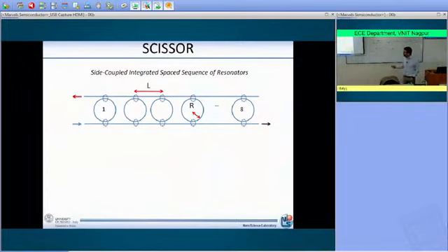So in this case, we have one microring resonator, another microring resonator, another microring resonator, and the spacing between those microring resonators is fixed. To give you numbers, the radius here is 7 micron, and the spacing can be 10 micron. Okay? And now we put these microring resonators into a self-pulsing regime.